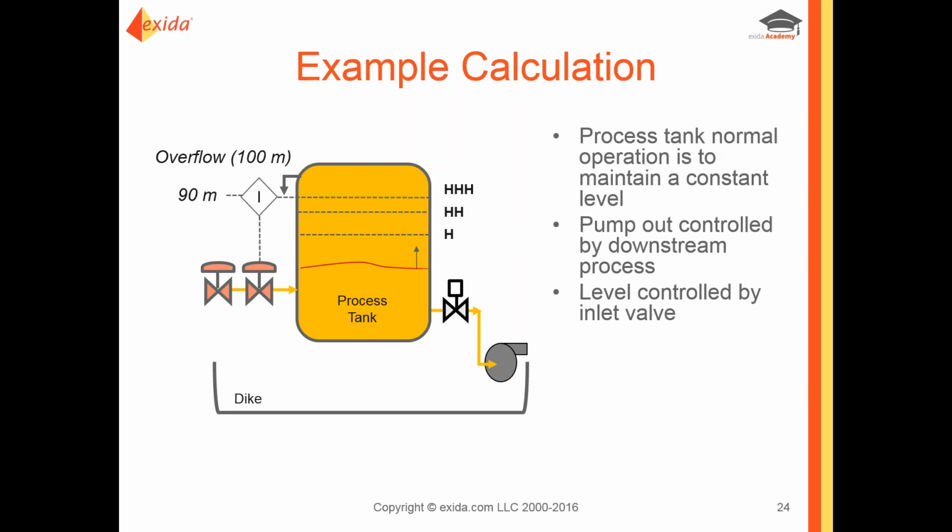And then we have a level control valve there on the far left, the one that's not connected to anything. I've not shown any of the basic process control details in this graphic, but it's that far left one that controls the inlet valve. So we have a process control system that is independently measuring the level in this tank and controlling that valve.